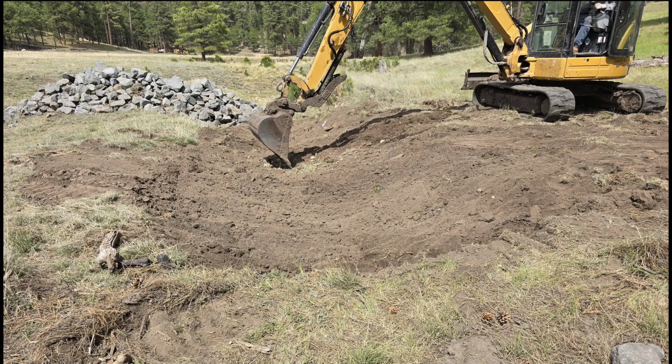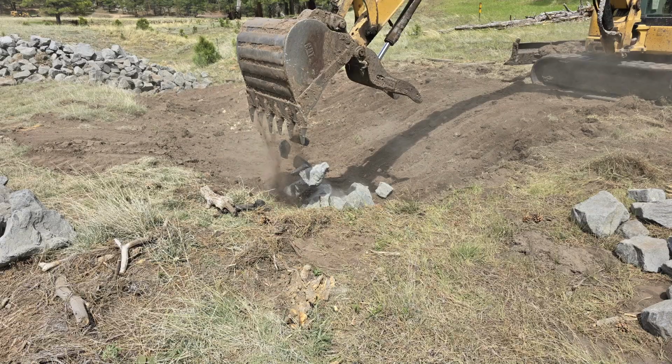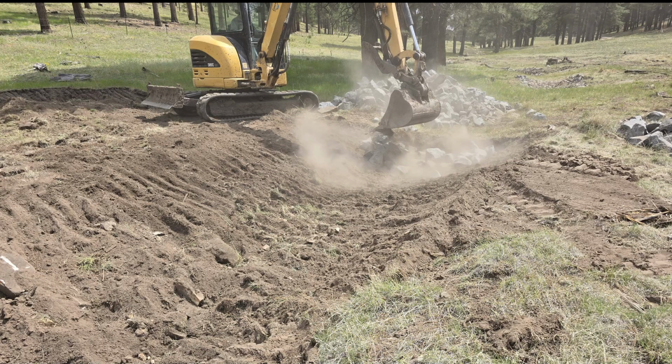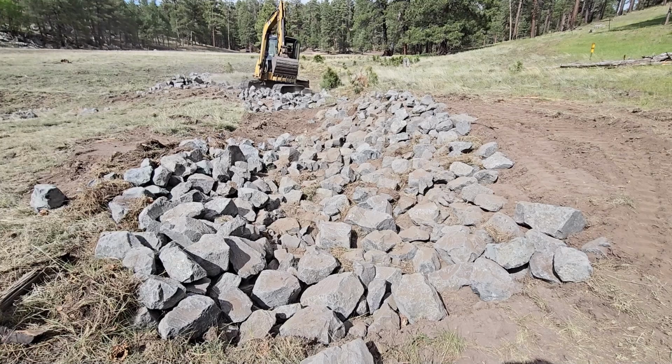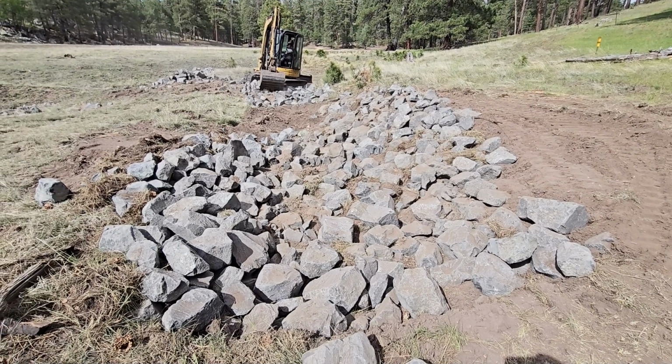This is done to make room for the thickness of rock that we placed to armor the slope. Rock is placed on the exposed soil within the reshaped floodplain of the stream. The rock is placed in the channel and up the sides of the stream banks. Don uses a digging bucket with teeth to place the rock at a layer about 12 inches thick.